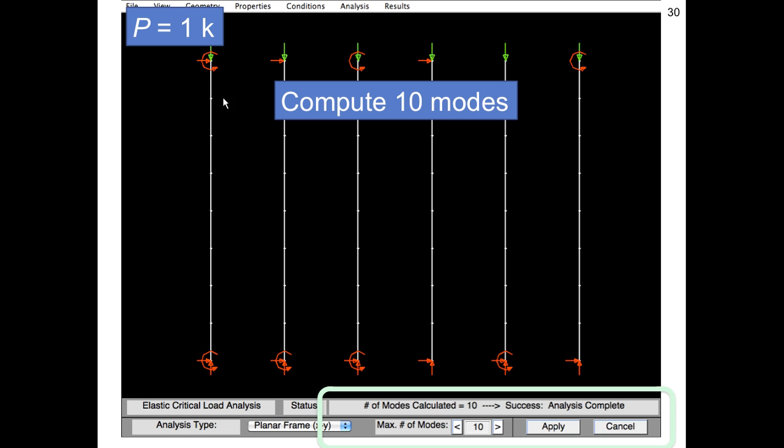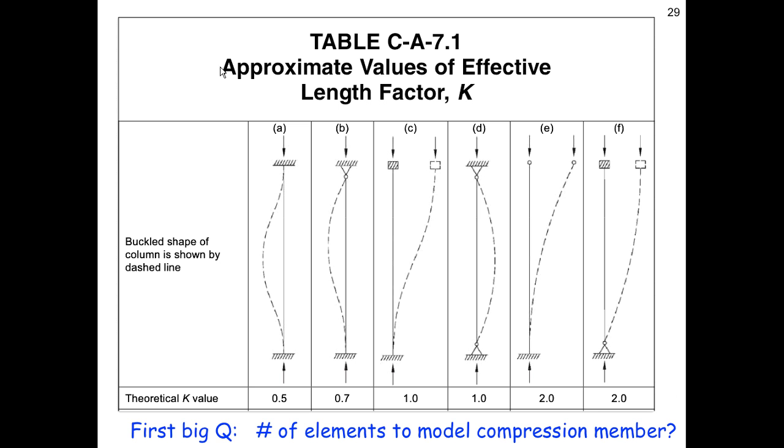And then coming across the top, I need to, of course, permit vertical movement so I can actually buckle the column, but I've got different possibilities on the amount of horizontal restraint. These have horizontal restraint, the third one doesn't, the fourth one does, the fifth one doesn't, and then also different amounts of rotational restraint. By changing those boundary conditions, I'm back to getting the boundary conditions that are consistent with the picture that I was showing you before.